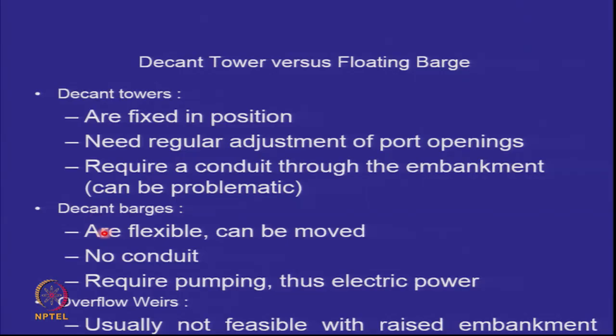Decant barges, they are flexible and can be moved. There is no conduit through the base of the dam, so they look very good, but they require pumping. And thus they need power. So in India, we are still using decant towers.